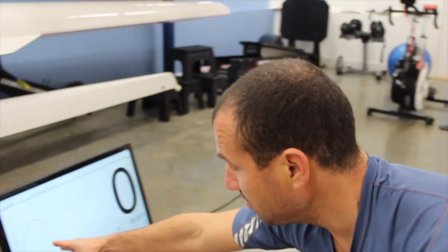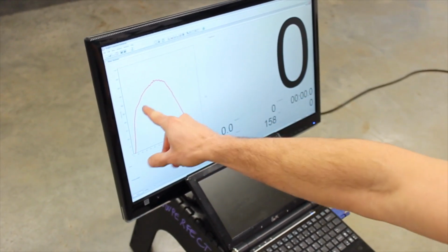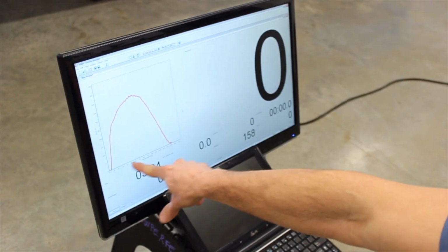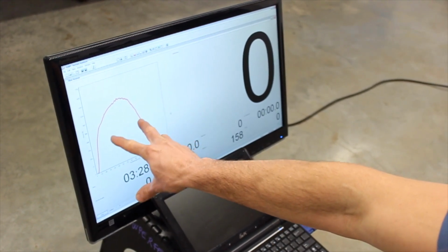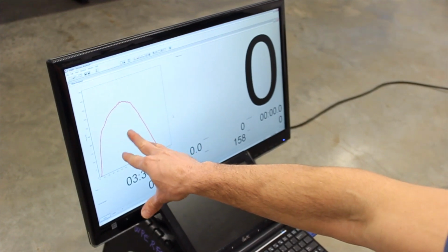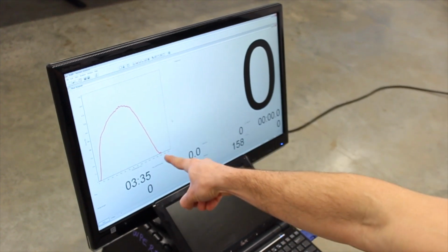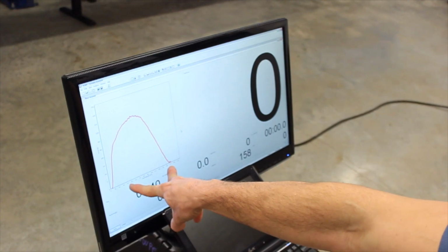Now that you know what the peak force is, I'm going to quickly give you an idea of the role of the peak force in the whole power curve. Here we have a power curve, and the vertical axis is force in newtons. The highest point is the peak force, and the horizontal axis is the stroke length in centimeters. The area inside of the curve is the work we do, the joules per stroke, the energy per stroke. Normally to have a big thick power curve, you need to have a good peak force, and you need to have a good length of stroke.